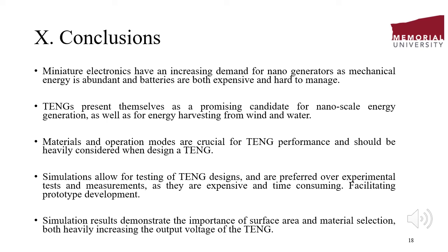Simulations allow for the testing of multiple triboelectric nanogenerator designs and are preferred over experimental tests, which are often expensive and time-consuming. Doing simulations is particularly helpful as it facilitates the development of a prototype by making the process more effective and efficient. The simulation results demonstrate the importance of the surface area and the material selection, as they both heavily increase the output voltage when chosen adequately on a triboelectric nanogenerator.